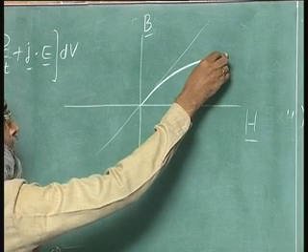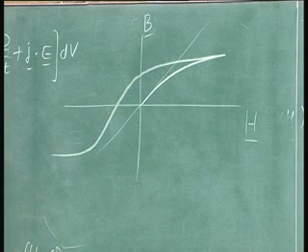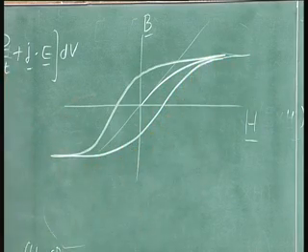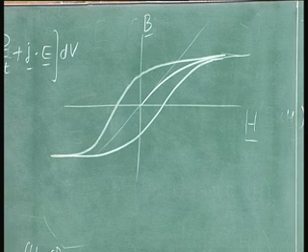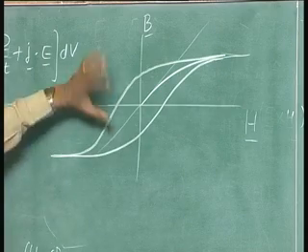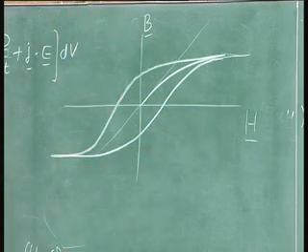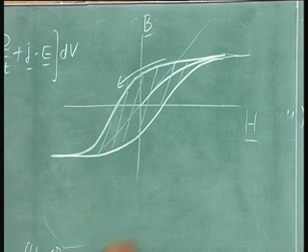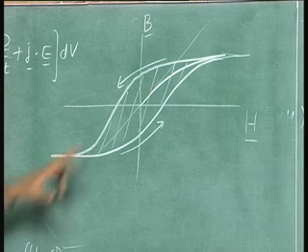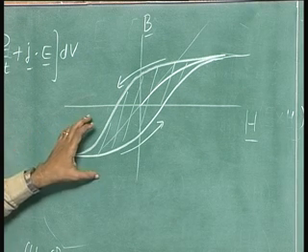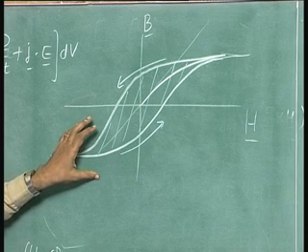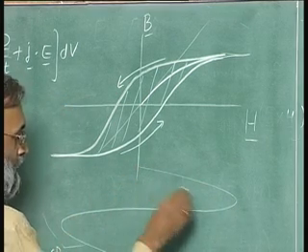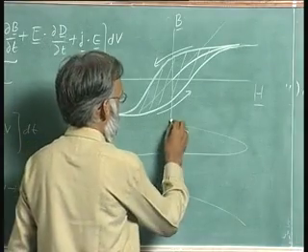And when you try to bring B down, you get an effect like this, which then gives you the standard hysteresis diagram. And however you do it, whether you do integral H dB or integral B dH, the area enclosed by the return and the forward curves is the amount of energy that is dissipated in any magnetic system due to a cycle of applied field. So, if the applied field were varying in time like this, let us say this is time and this is B or H,